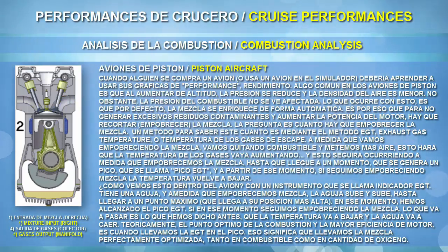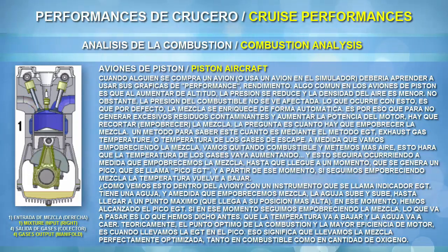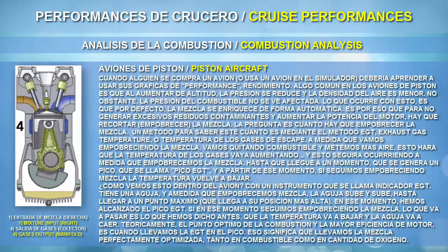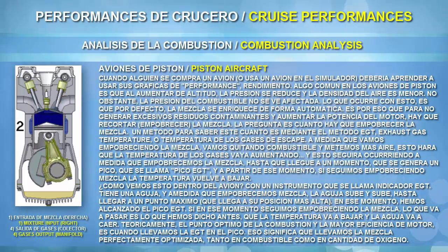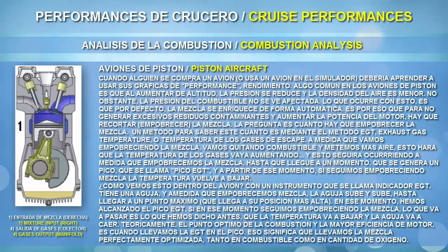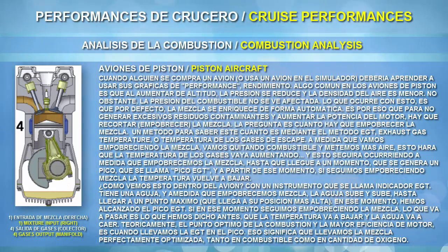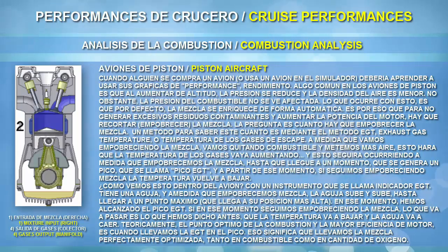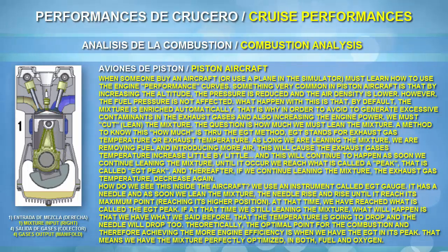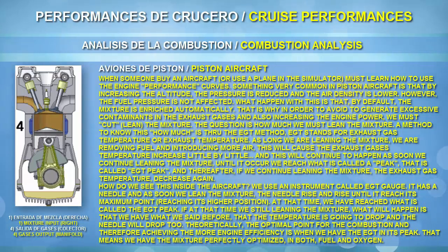And you know what happens? We have here different fluids. We have the fuel, the aviation gas, which is a liquid, is a fluid, and also we have the air, which is a different fluid. And you know what happens? Because the air density is lower, the mixture is enriched by default as soon as you ascend, because these changes in pressure do not affect the fuel. And for that reason, we can say that the mixture is enriched automatically as soon as you are ascending, okay?